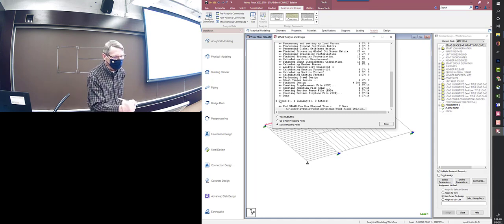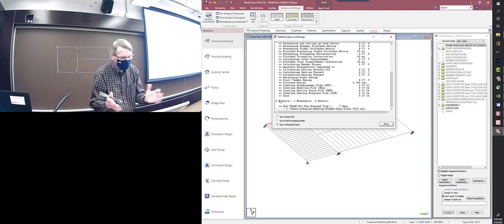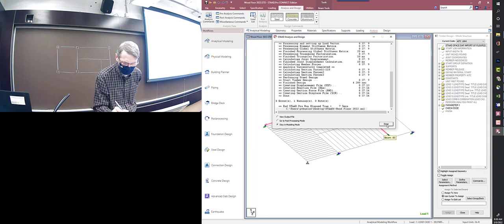If there are warnings, sometimes it'll warn you if you've got too many end releases. It'll give you warnings about that, which are kind of a nuisance. Fortunately, I think we corrected all those, so we don't have that. The one warning I'm getting now is because I'm using the area command. They're trying to replace it with, I think, a one-way command or something, but it's much more complex to use. For this simple example, the area command works okay, so we're just going to use that.